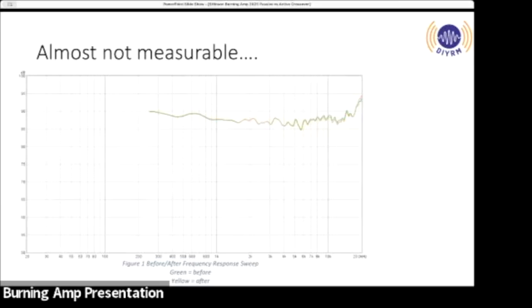They're typically, the bipolars are plus or minus 10%. So a lot of folks I've seen trim, they'll put a cap. It's not truly a bypass cap because that doesn't work at these frequencies. That just doesn't. The leads are too long. That self-resonance, again, that Mark talked about, I think I talked about this last year, that self-resonance kicks in, and that bypass cap of 0.1 or 0.01 microfarads that you're putting in parallel with that 20 microfarad film cap, those leads are long enough, it doesn't do you any good whatsoever. Okay.